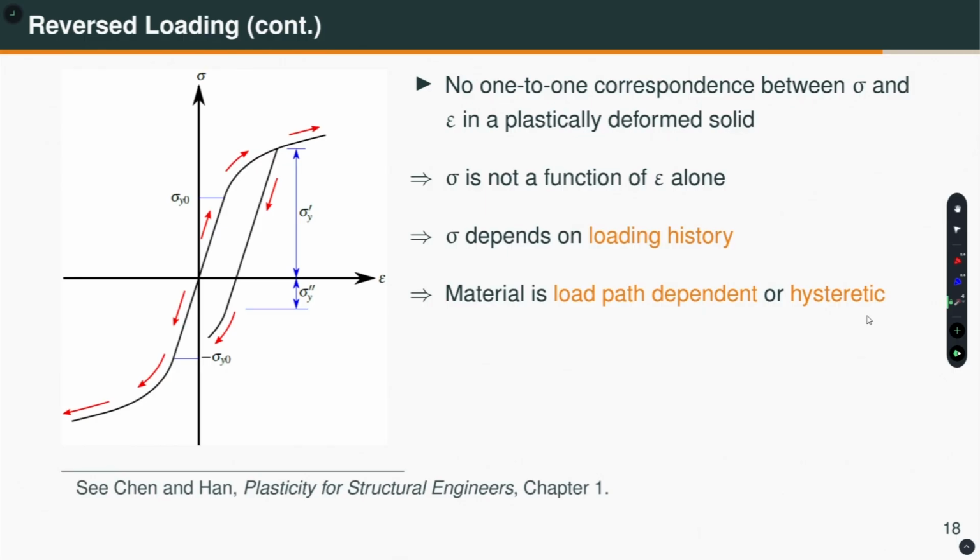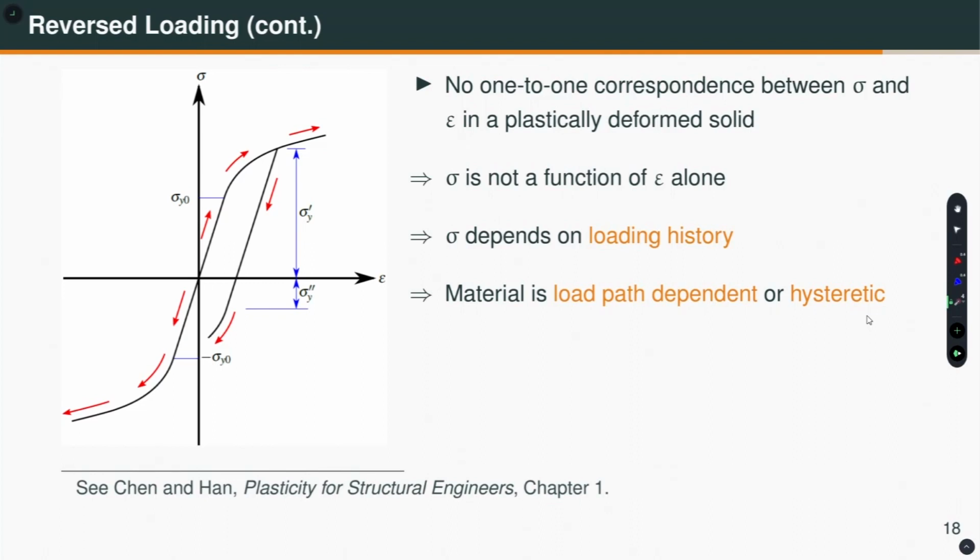So, therefore, if you recall, when we were talking about path dependent versus path independent state determination in the previous lecture, you will see that the Newton-Raphson iteration that we are doing is just for our convenience. We are trying to determine the equilibrium position. It is a numerical method. It is not the actual behavior of the material. Therefore, we have to always do path independent state determination, because the material shows path dependent or hysteretic response.